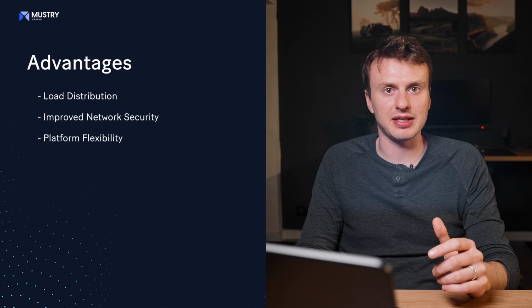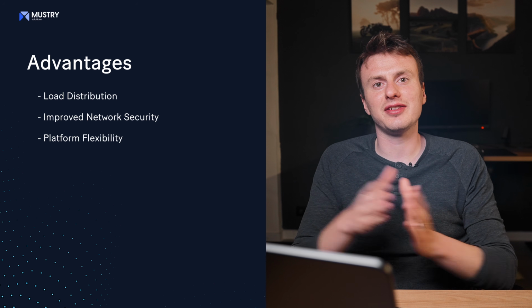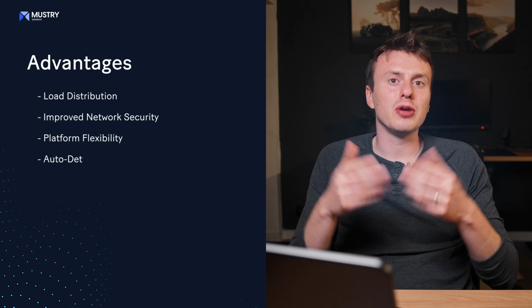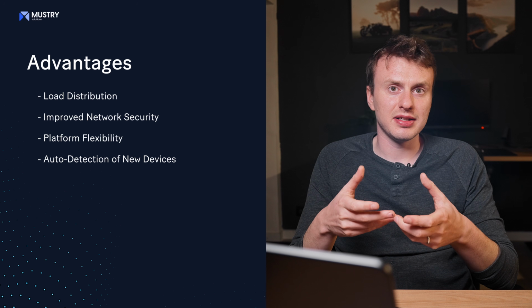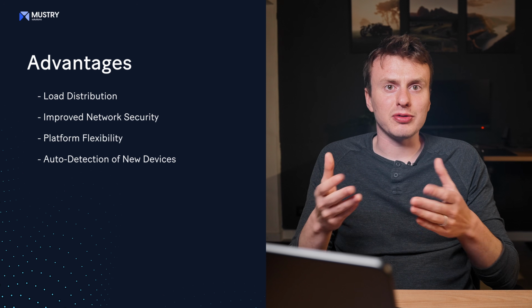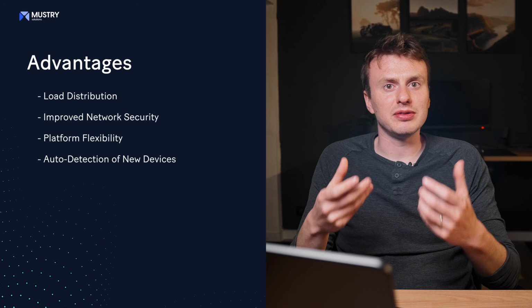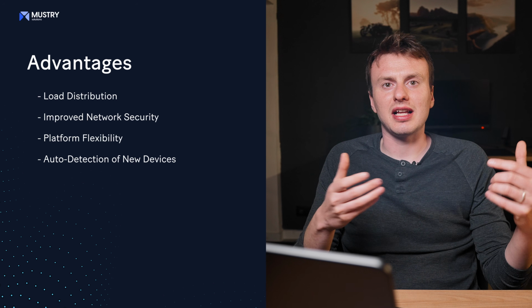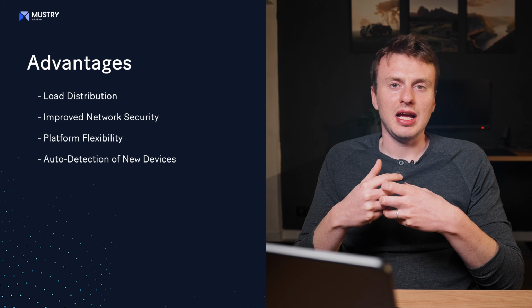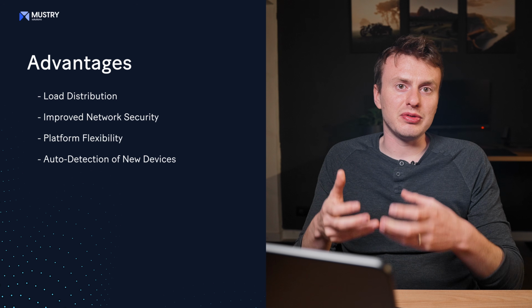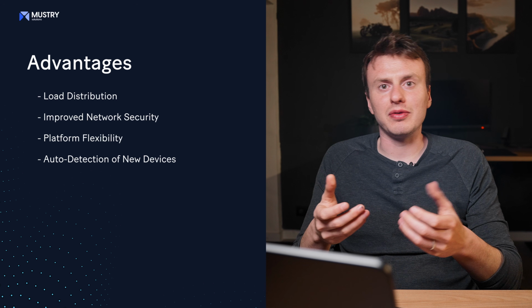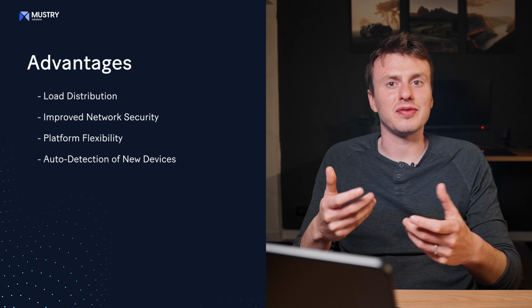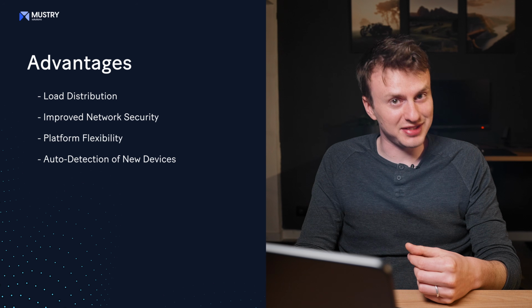The fourth advantage of this system is auto detection of new devices. Higher level systems can automatically detect and integrate newly connected devices that come in through Sparkplug B, and this reduces the manual configuration and speeds up the deployment of additional machines or sensors.